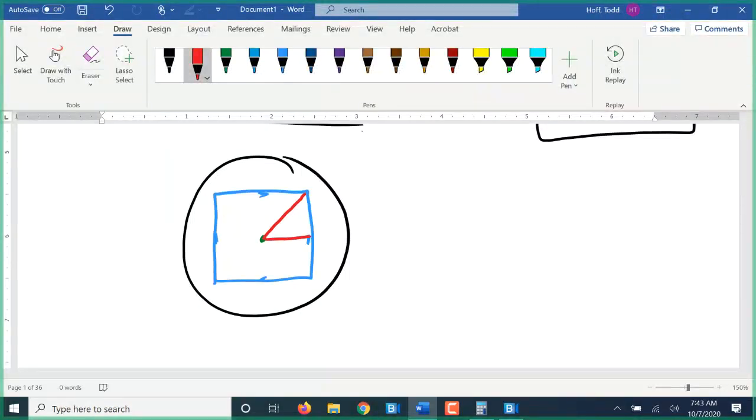So in geometric dimensioning and tolerancing, rather than giving a plus or minus for the x and a plus or minus for the y, they give what's called a runout or circular runout, where they say that we have to be within this distance of the center no matter what the direction is. So rather than giving a plus or minus in the x and y, we give a radial distance from that desired ideal location.